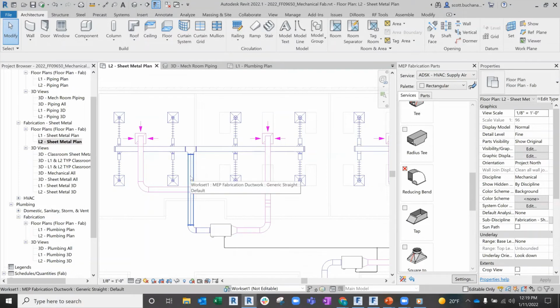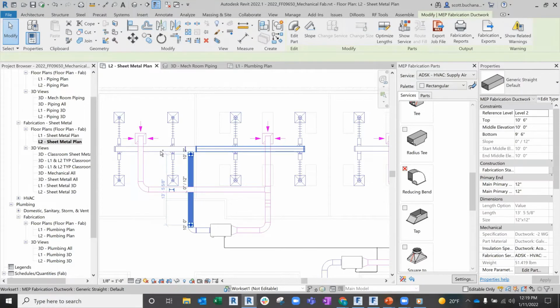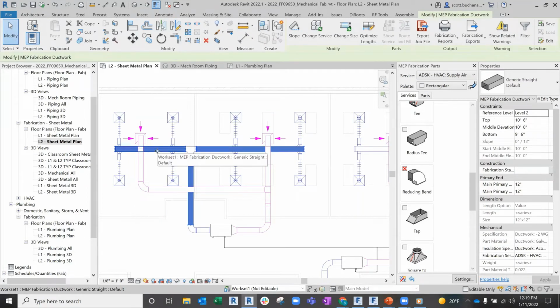Now, one other thing that's going to take place, I mentioned it's a one-to-one swap, right? So whatever that straight length of duct was, it's going to put a straight length of duct in that same place. Those from Sheet Metal World on this are looking at saying, okay, well, we do not fabricate a piece of duct longer than, it could be 4'11", 56 1/4", whatever your standard shop is, but we do not do that. So we understand that, and that's why we can pick our duct runs after they've been converted.